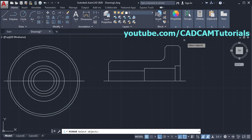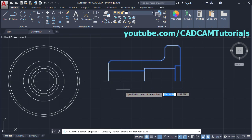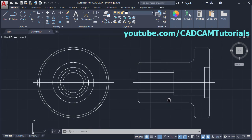For that, we will use crossing window. Click on the right side in empty space and take your cursor on the left side. Then click, enter. Then the first point of the mirror line will be this endpoint. Click there, take your cursor on this right side and click. And erase source object, no. So this object is ready.